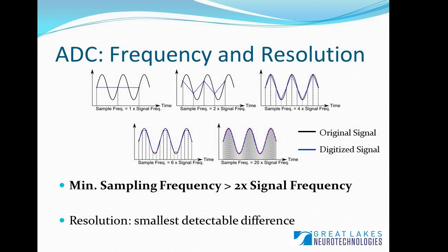Whereas in the case of using EMG for a motor control or computer control device or application, where typically the signal is rectified and integrated anyway, we're not so interested in the exact fidelity of that EMG signal so much as detecting the presence of it and magnitude of it, in which case sampling at a lower frequency will allow us to do so on perhaps more channels or open up the possibility of wireless